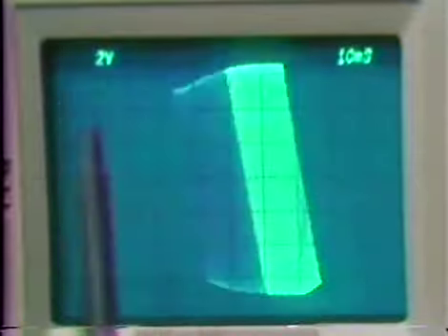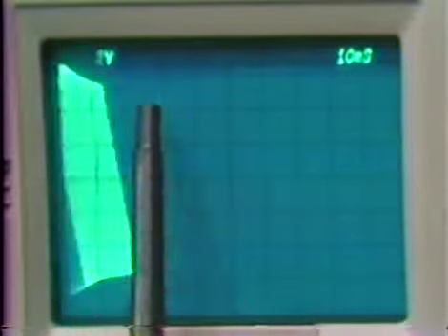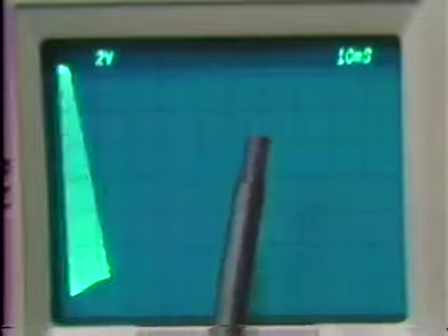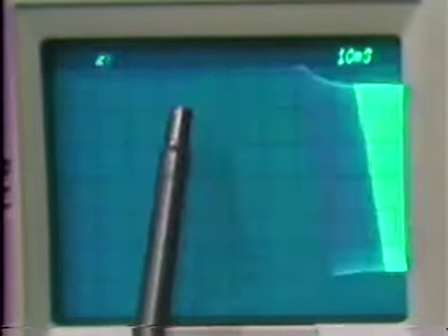Again, here we see the exponential changes. Commanding a small amplitude, then commanding a larger amplitude, operating about 5 volts. For this small a signal, things are relatively symmetrical. We could estimate crossover frequencies in the control loop by looking at the time constant of this exponential.